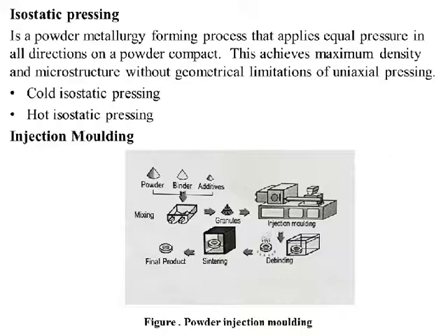Injection molding. Injection molding, also called powder injection molding, PIM, is an efficient method for high volume production of shaped components from powders. So we can produce products in large volumes by using the powder injection molding method. This is a derivative of polymer injection molding. The same technology is adopted for preparing powder metallurgy parts also.